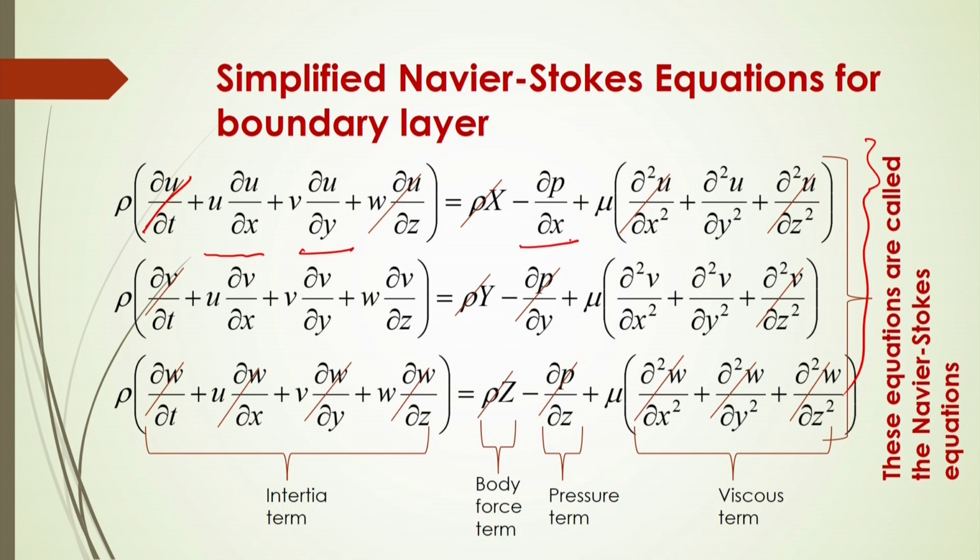In the x direction there will be a change of pressure, and another part for the viscous effect. Of course, in the y direction there will be viscosity, because this shear strain will be in the y direction, with the velocity gradient in the y direction. Because of that, you can get the viscous effect or viscous force. So, in that case what will be the component? Mu into dou 2 u by dou y square.